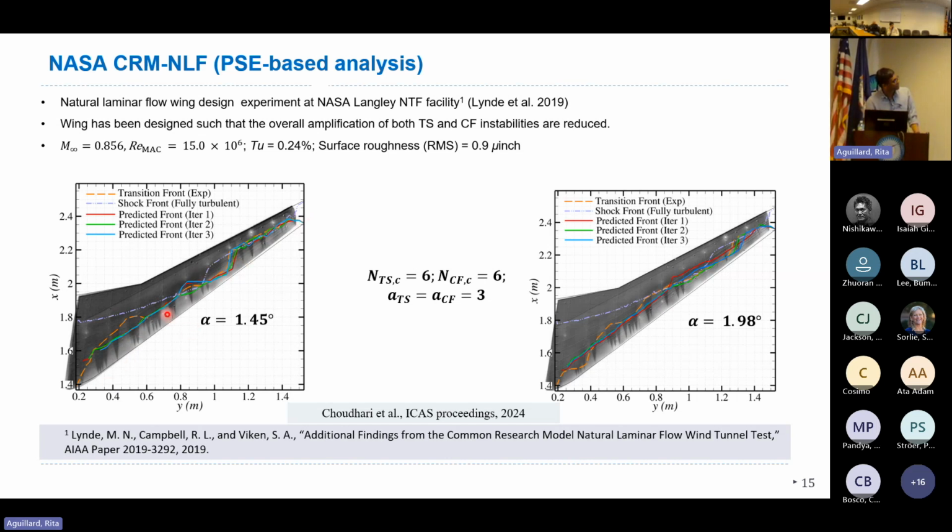Through the iterative analysis, what we did see is, as we go outboard, the transition is entirely shock limited. In the inboard, it's a lot of TS. There is some crossflow near the break, but the approach is able to converge quickly and capture the general trend very well across different conditions. And at least the coefficients were not too different from the juncture flow model as well.